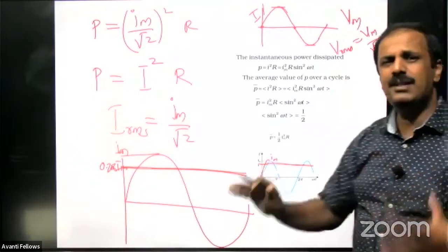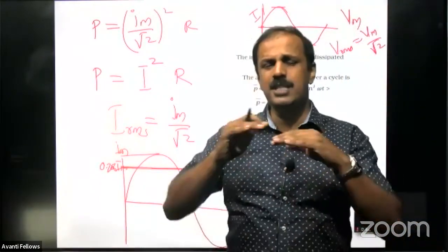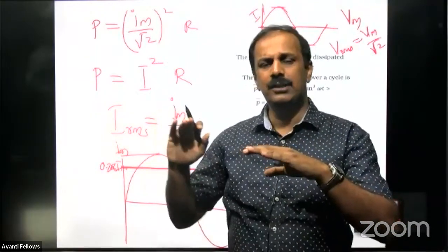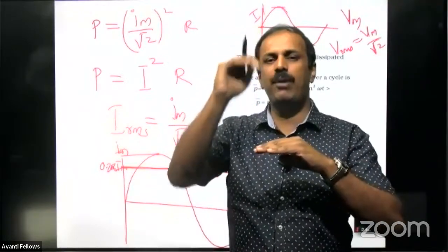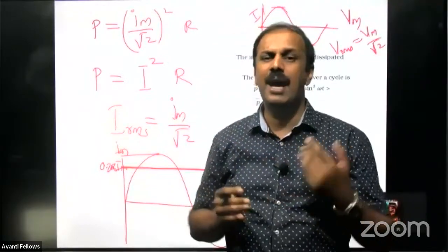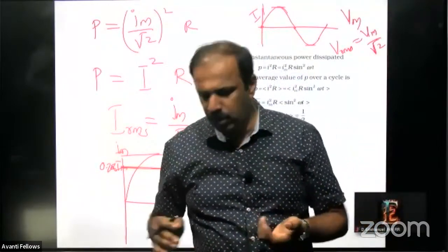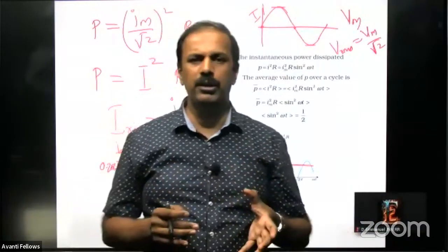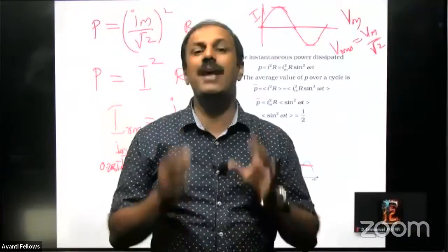And the basic thing is, when you compare AC and DC, the AC will vary from 0 to the maximum value and will go to the negative side also. So the effective value of AC is that maximum value divided by root 2. That is called the RMS value. But one thing: when you get a problem, AC voltage of 100 volt or AC current of 3 ampere, this AC value is the RMS value.